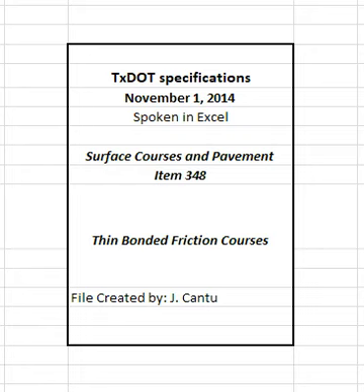2.6.3 Lime and liquid anti-stripping agent. When lime or a liquid anti-stripping agent is used, add in accordance with Item 301, asphalt anti-stripping agents. Do not add lime directly into the mixing drum of any plant where lime is removed through the exhaust stream unless the plant has a baghouse or dust collection system that reintroduces the lime into the drum. Lime added as mineral filler will count towards the total quantity of lime specified when the plans require lime to be added as an anti-stripping agent.